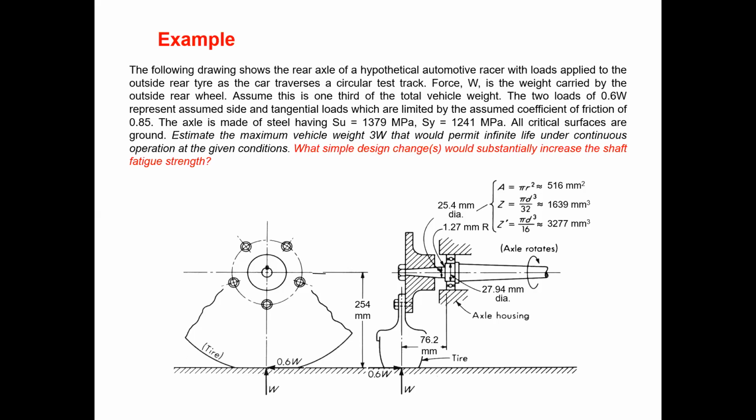Okay, so anyway, if you have that kind of idea, you need to answer according to that. Because if you change the diameter or something, it will feel like you are going to change the diameter of the whole section. So significantly, you mentioned the stress raiser areas. All the calculations we did are around this area, because we are not going to calculate the stress here or somewhere else, because normally the stress raiser area is the higher stress area. So we need to consider the higher stress area, then other areas will not be significant. Okay, is it clear? Yes, sir. Thank you.